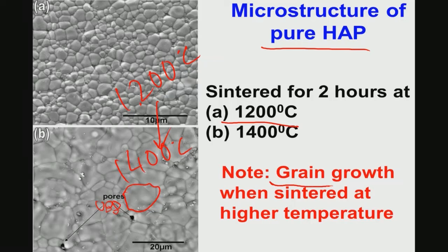And this bimodal grain size distribution is certainly because of the grain growth when the sample is sintered at higher sintering temperature. So, this places importance on correctly and appropriately selecting the sintering conditions in terms of both temperature and pressure. If you do not have sufficient understanding of the sintering process, and if you arbitrarily use the sintering conditions by hit and trial method, then what will happen?